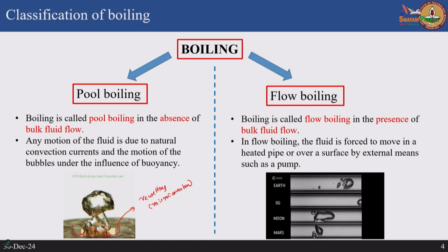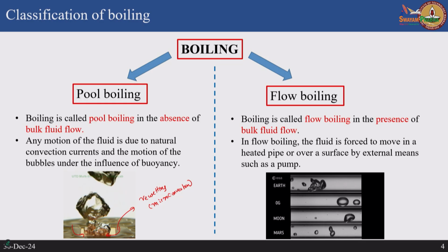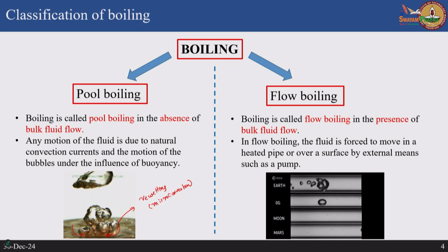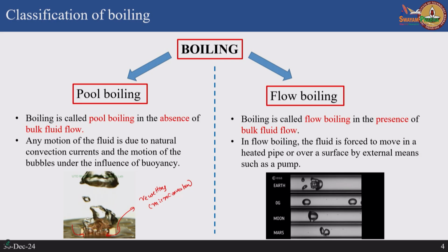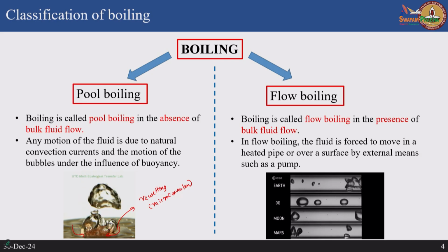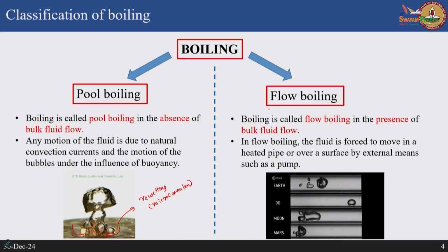So, you also have to circulate the liquid through the heat exchanger tubes, and this becomes what is called flow boiling. For example, you have circular tubes and you are pushing flow through these tubes. Along with the convective motion you also have a phase change, because locally you are heating the fluid above its saturation temperature. So, there is also boiling. Boiling plus convection together is called the flow boiling process.